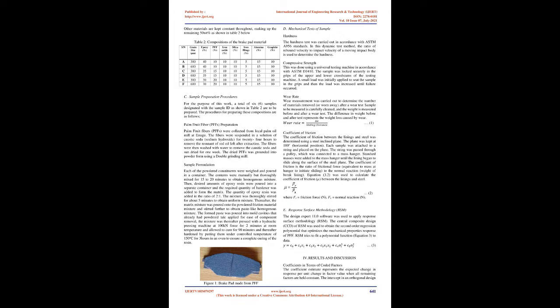In the study, the mechanical and physical properties as well as the static and dynamic performance compared well with commercial asbestos-based lining material. Studied the friction and wear of friction materials containing 2 different phenolic resins reinforced with aramid pulp, investigated the friction and wear characteristics of automotive materials containing 2 different phenolic resins, a straight resin and a modified Novolac resin, using a pad-on-disc type friction tester.